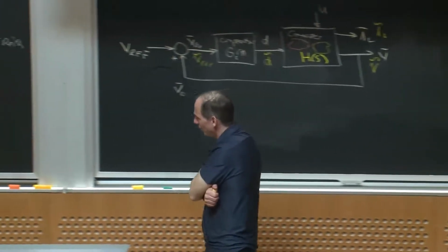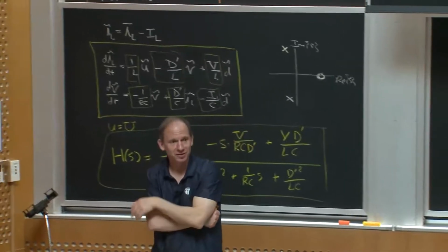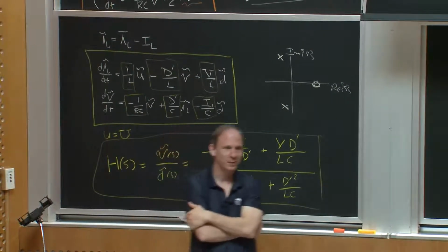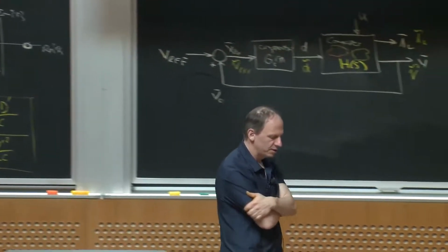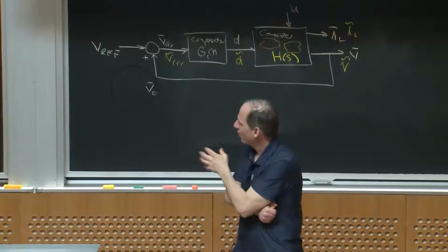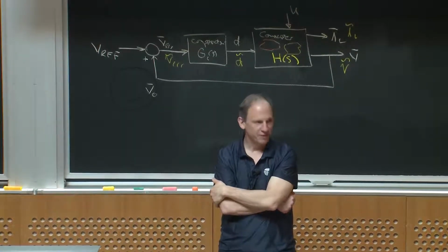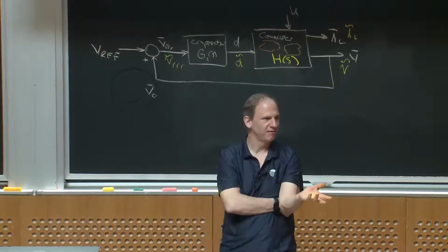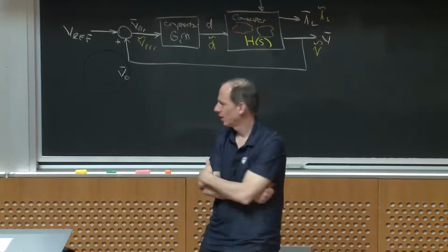But you could say, well, okay, you're mathematically finagling a bunch of stuff. Can't you just do a version of a model that's not going to have a right half plane 0, right? Like, why does life have to be difficult? And the answer is, the mathematical model you get actually very nicely reflects the physical dynamics of the system. It's not accidental that there's a right half plane 0 in the equations. It's intrinsic to the behavior of the system, okay?